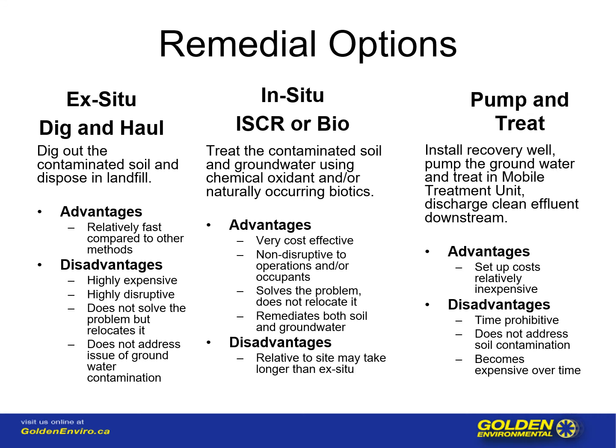One of the other issues is that of groundwater, as we mentioned earlier. If there is still contaminant in the groundwater, if the water table rises, then it will smear what contamination is left in the water table throughout your clean zone. So digging and hauling is not a guaranteed method of remediation, although none is guaranteed. These are things to look out for when you're doing a dig and haul scenario only.